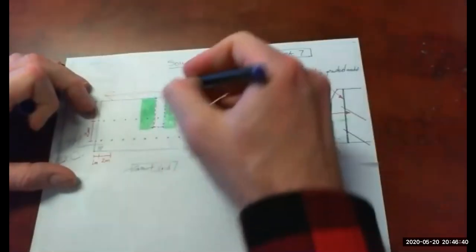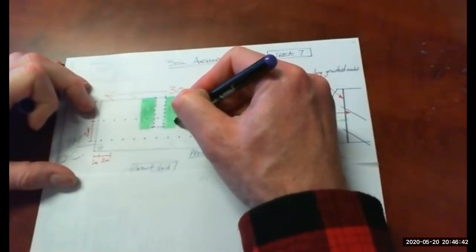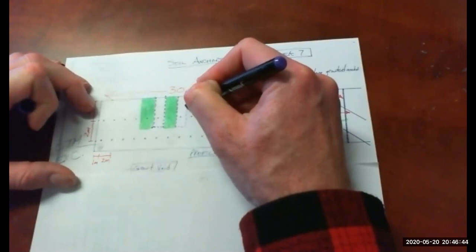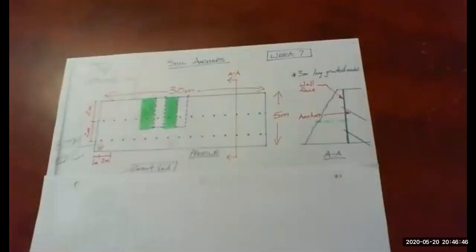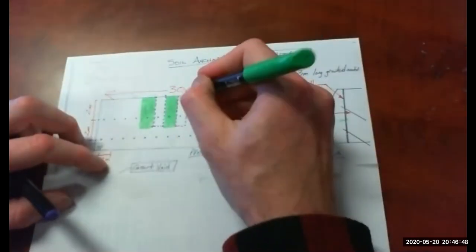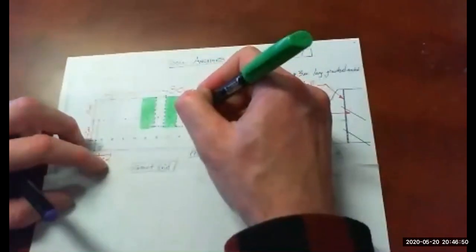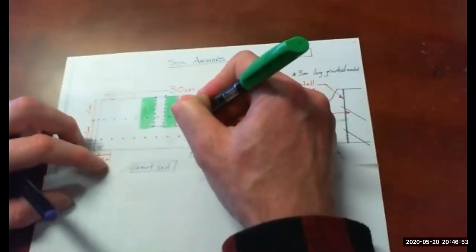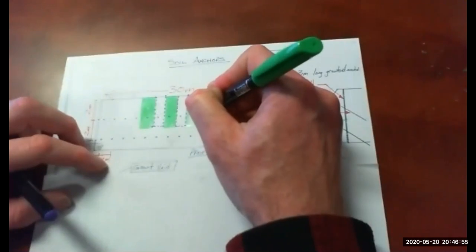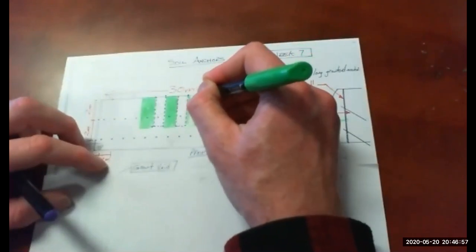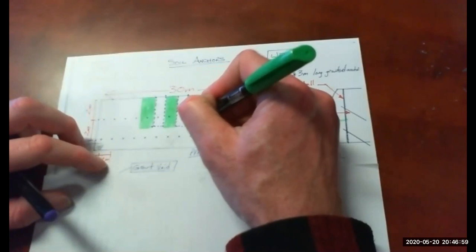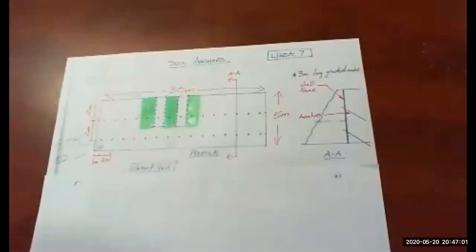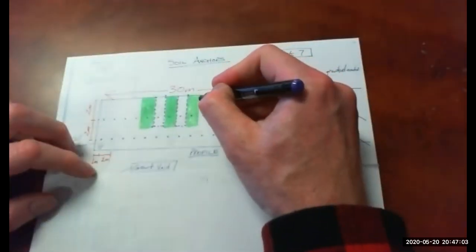And then similarly, we would skip the next one. So you would do this all the way along until you've excavated out every second anchor location on the top row. So I won't draw all these in, but you get the idea.